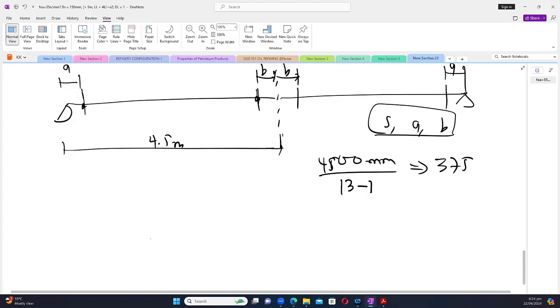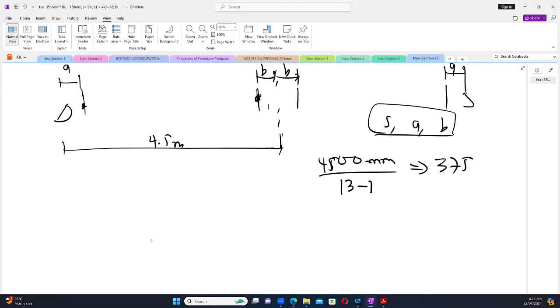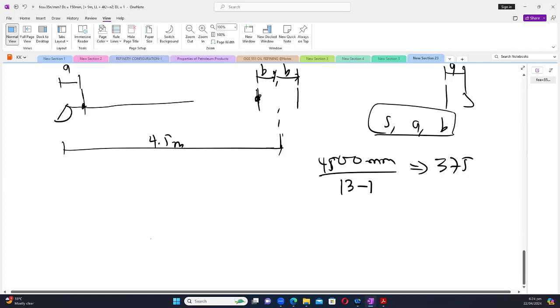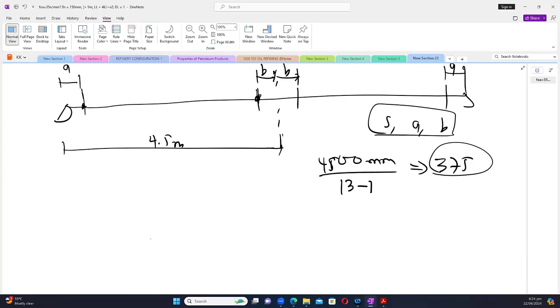This is a perfect answer. Just that if you use that, there will not be any value for A and B, and the two stirrups will be lining up here. So I don't want to use it. Even though it's correct, if I do that, this thing here will now be here. Okay, so I'm not doing that. I would rather reduce this to maybe either 300 or 320. So we can make it 300 or 325. 350 will not be too. Let's make it 320.